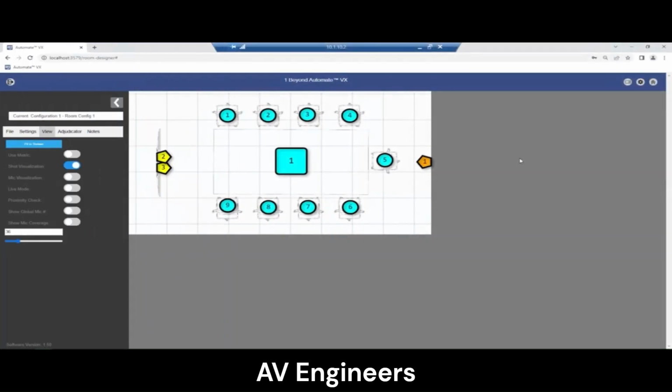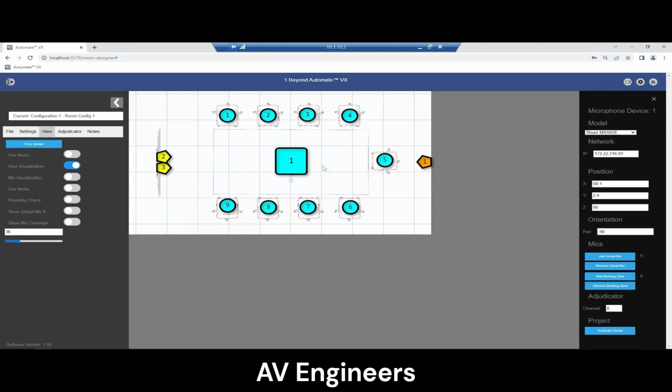Blocking zones are used to avoid unnecessary camera switching caused by ambient noise sources in your room. To add a blocking zone to your design, select the microphone device. On the right-hand side, select Add Blocking Zone. Then you can click and drag the gray blocking zone to the area of the room that you'd like to ignore. For example, the doorway in a room or a loud equipment rack.